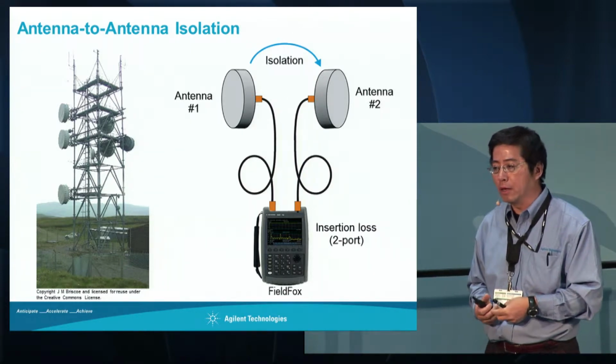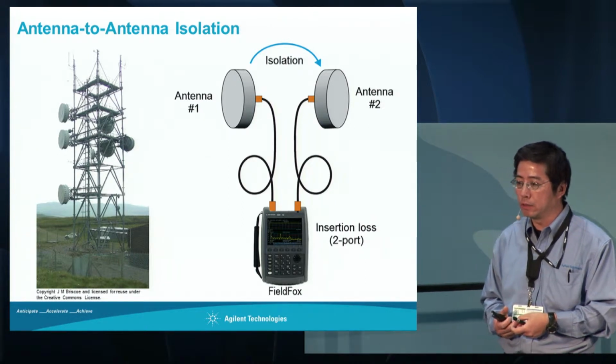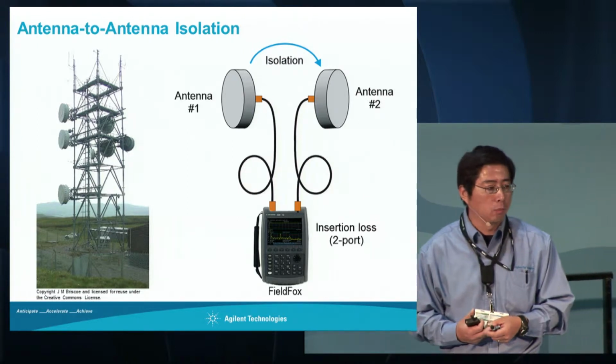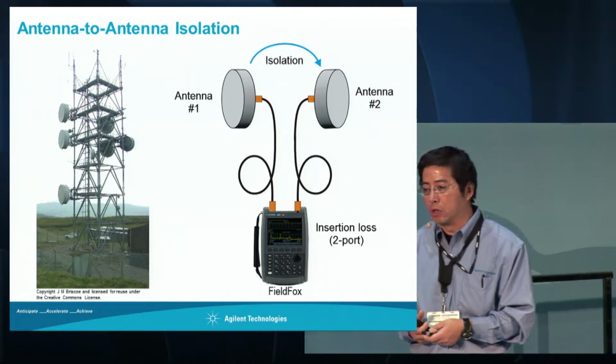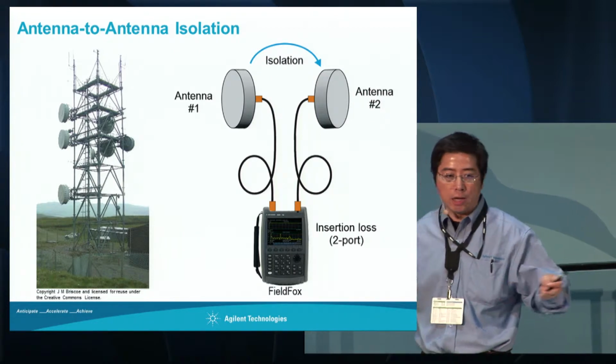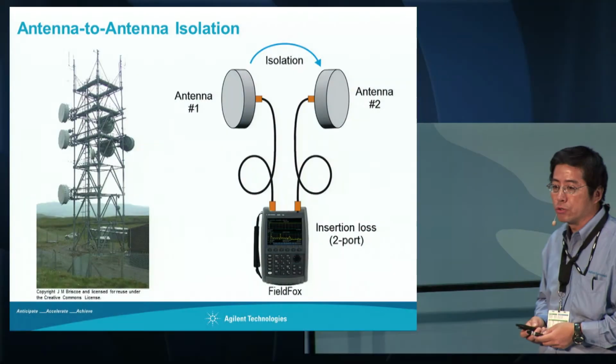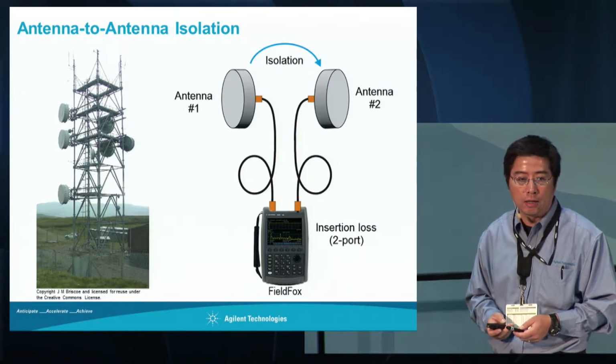So that puts a great challenge on the test engineer or technician in the field: how to make sure the measurement is accurate. Also, the industry uses a lot of repeaters, where it's even more critical to have good isolation. For example, your repeater's two antennas require about 90 dB isolation. If you have less than that, you create an oscillation between the two antennas. So you bring the whole noise floor up, and not just damage your equipment, you can create interference for the whole system.